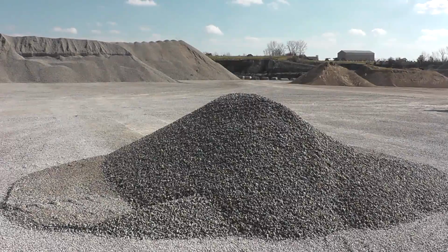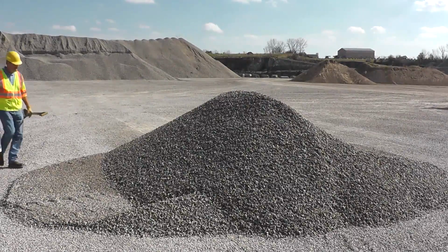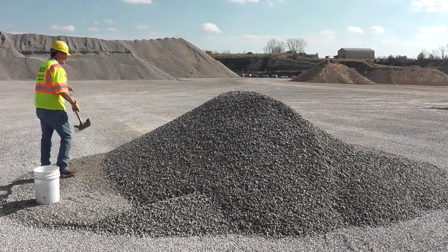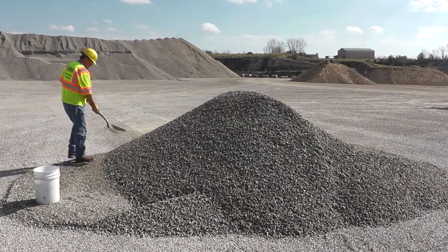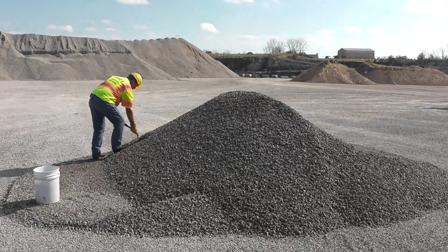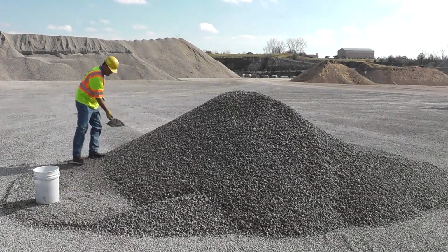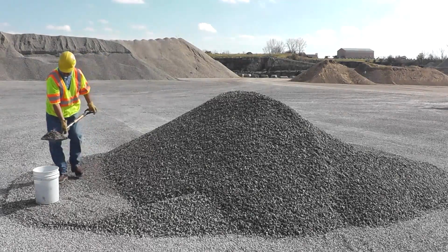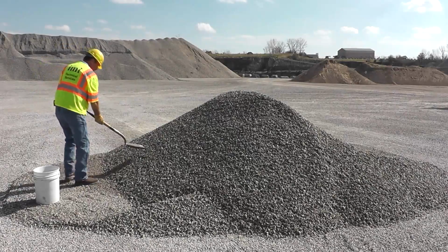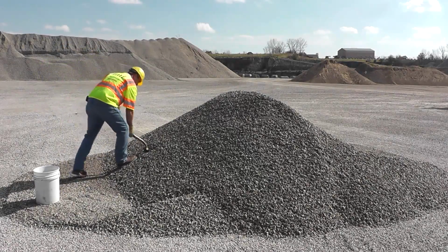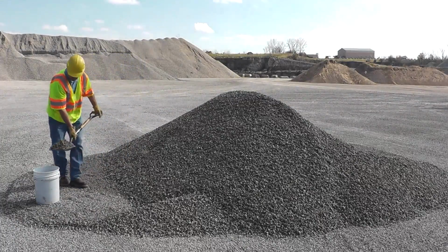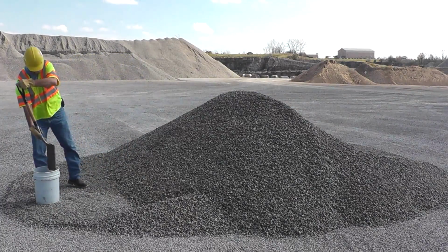The inspector shall insert the shovel horizontally into the sample pile, keeping the bottom of the shovel parallel to the ground until the shovel reaches full depth. Then the inspector carefully raises the shovel horizontally, keeping the bottom of the shovel parallel to the ground and taking care to keep as much of the sample as possible on the shovel. Each shovelful of material is placed into a container and then taken to an area to be split down into the proper test sample size.